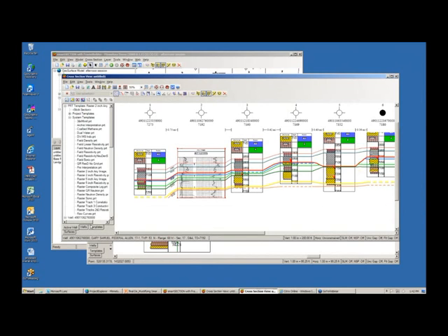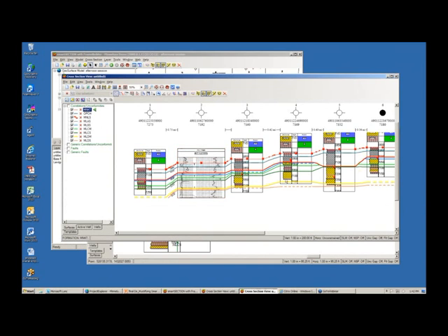Now, in contrast, on the well-to-well cross-section, when you pick a surface, I'm just going to click on my Surfaces tab and pick the Minikata here. What you will see is a solid or a hollow square at the site of each well on the well's borehole. This represents the formation top that was picked on the actual well itself. A square means the well log image is on a well-to-well cross-section, meaning the cross-section is actually going through the actual side of the wellbore.